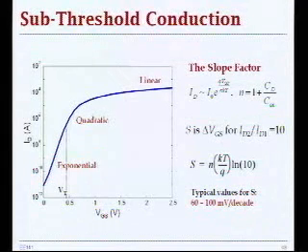It's important to analyze the transistor when it has enough current to perform switching behavior that defines Boolean functions and provides useful computations. You might assume that when the gate to source voltage is less than the threshold, your device is completely cut off. That may have been true 10 years ago, but these days, in modern processes, you have more and more sub-threshold conduction, manifested as leakage current.